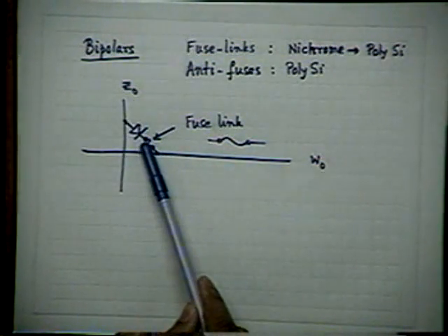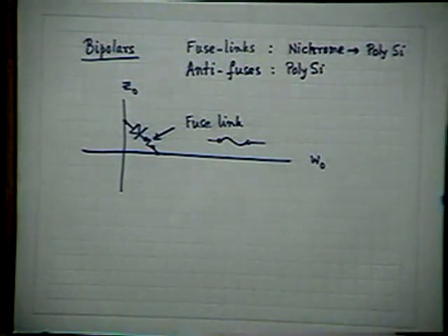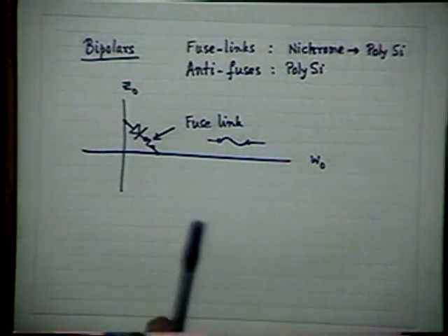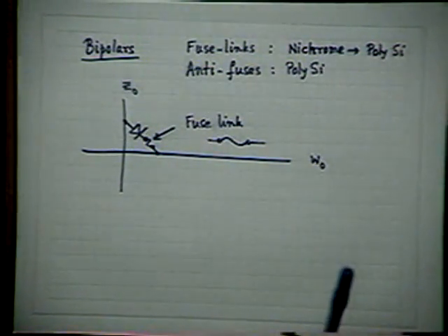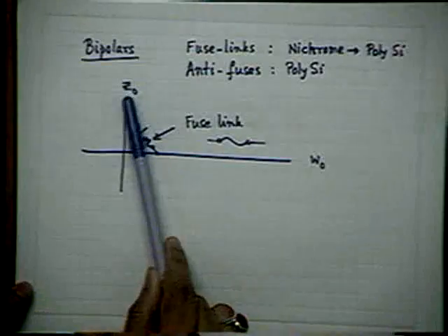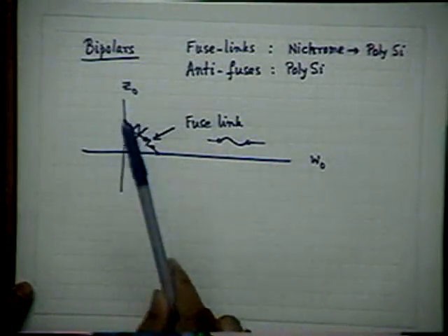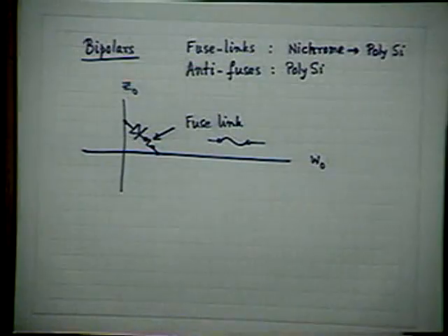Fuse gets blown off because of the heavy current, and you get the off. That means the normal. So wherever needed, I remove the diode this way. I remove the diode connection, not remove the diode. I remove the diode connection this way by momentarily raising the voltage at the particular node, particular input, decoded output. There must be switches, that is a standard technique in MOS, in memories. So which will isolate from the main decoded output and apply a large bias for a short time.